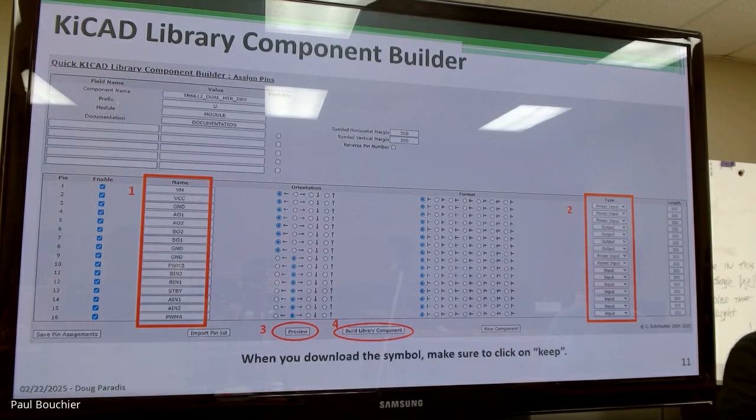And then, I can't read it. PWMB. This motor driver uses 3 pins to set the motor, 2 to set direction, and 1 to do the actual PWM on this particular module. So all of those are just inputs. And so that's the rest of them, I think. That's for the 2 different motors.